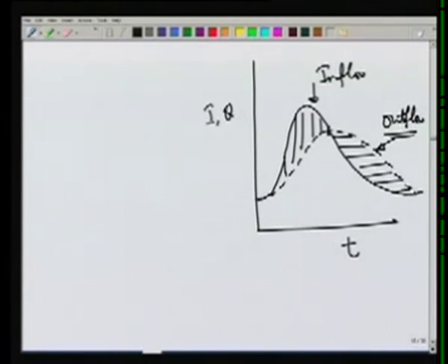the outflow is more than inflow, which means that water is being taken out of the storage, and the volume of these two should be same, because whatever additional water we have deposited into the storage here should come out during this time, and after this the inflow and outflow will be same at the initial level. So if they reach the initial level again, then they will maintain at that initial level, the storage will return back to its original position.